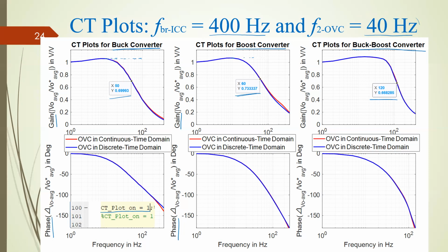And if you want to get the Bode plot using an average circuit diagram, not using the actual PWM circuit, then you would see the Bode plots of all converters would look similar, and they would be tuned nicely. But since we use the actual circuit, we have losses and non-idealities, and of course the value of D we used was computed considering the ideal converter topology. So that also makes some errors in the Bode plot or in the control tuning. Okay, but our time domain responses are better, and they are acceptable.